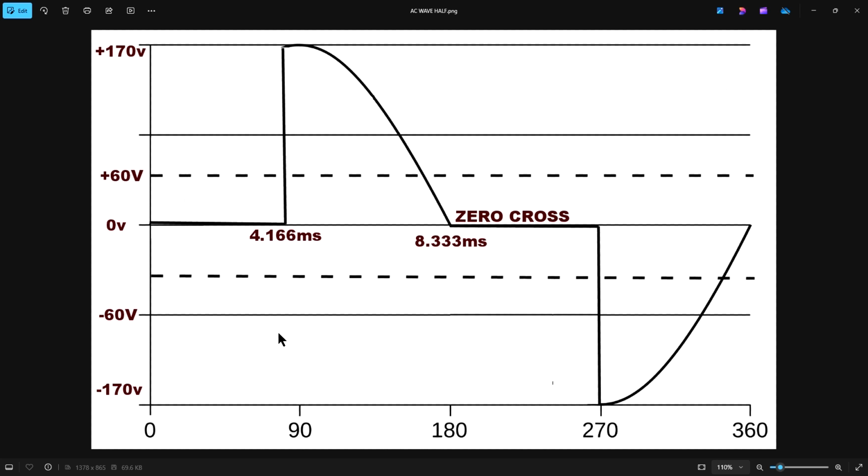Now, you could put a big rheostat in the wall that would drop the voltage resistively to turn the lights down. But what would be wrong with that? Well, the amount of power wasted turned into heat would be ridiculous. So that's a very inefficient way of doing it. On the other hand, this is a very efficient way to do it because we just leave the power turned off until we're halfway through. If we're dimming halfway, bounce it on, let it run through. We're not generating a bunch of heat. The power is all going into your lighting fixture.